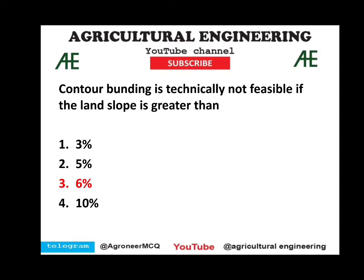Contour bunding is technically not feasible if the land slope is greater than 6%. If your land slope is less than 6%, then you should go for contour bunding, and if your land slope is greater than 6%, then you have to go for terracing. So you just compare the slopes and the rainfall, these two things, with bunds and terraces, so that you can easily remember these things.